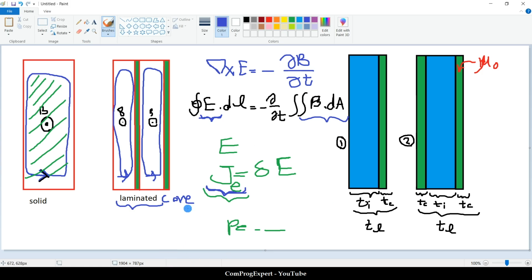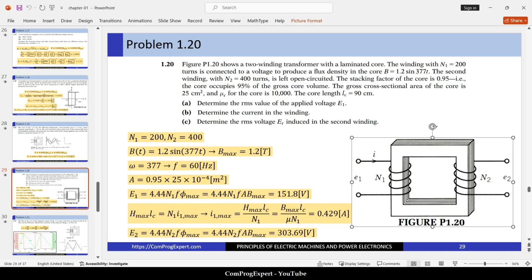And consider that in the case of transformers, power transformers, distribution transformers, the frequency is not even too high, 50 hertz or 60 hertz. But in these cases, we have a high amount of eddy current losses if we use solid cores. So you can realize how important eddy current is even for low frequencies.